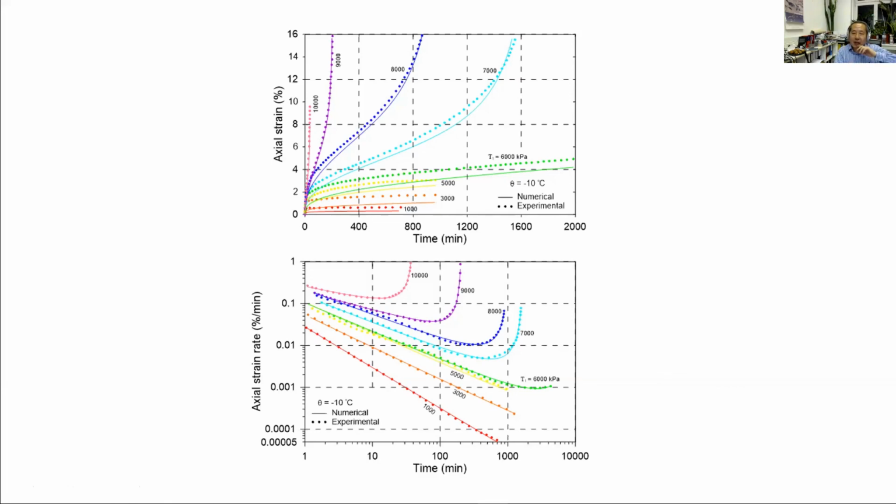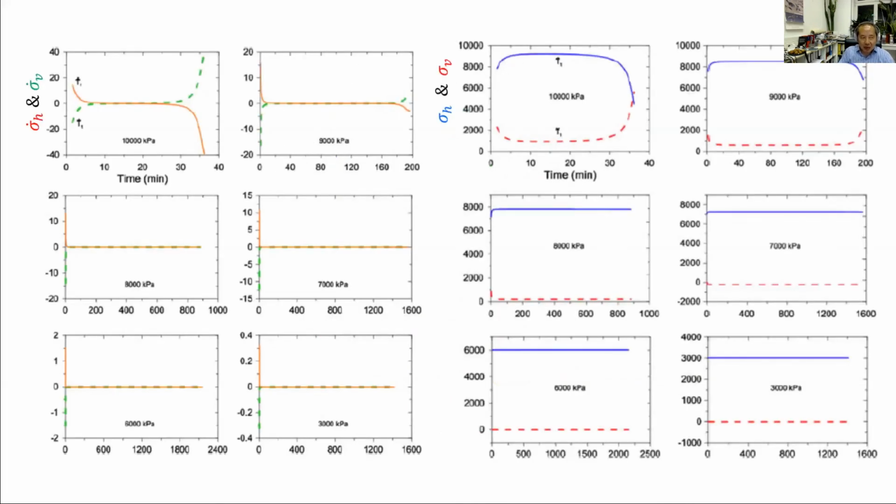Nothing happens there. Because we have this stress decomposition, we got two stresses. Each constituent model works its own stress. Only through the equilibrium they come together. You have a look at the stress rate, like on the left-hand side, and on the right-hand side, I've got the stress. Interesting thing here is, even during this creep test, the two stresses are not constant.